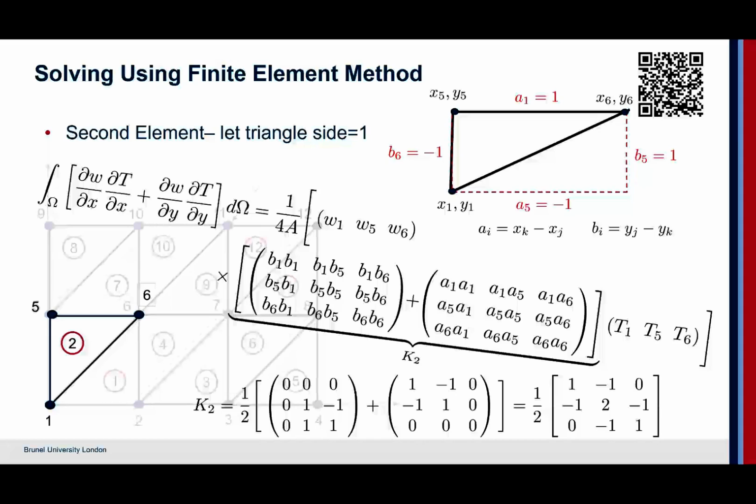That is, we only have to do this once because we have exactly the same triangle across that. We know that the form of the stiffness matrix is identical for all of those. Now this is the same process we had when we defined an expression for individual matrices, which were minus 2 over h on the diagonal and 1 over h off the diagonal. Exactly the same thing now here with individual components.